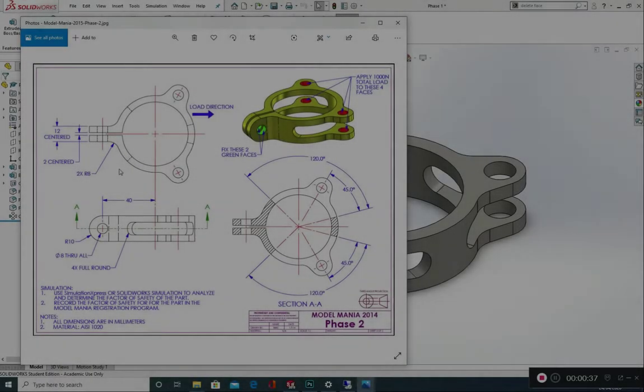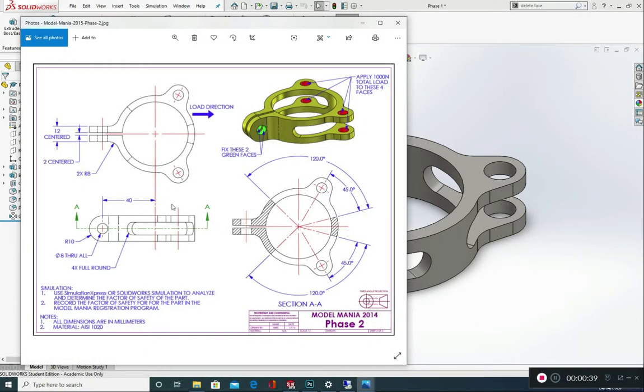Okay, so you can see from this particular engineering drawing that we've got one dramatic change to make here, and then some FEA analysis to complete with applying some loads. So this is the point here that we need to address. It's almost been twisted 90 degrees. So we've got some dimensions here. We've got a gap that splits this particular feature here, which is 2 millimeters.